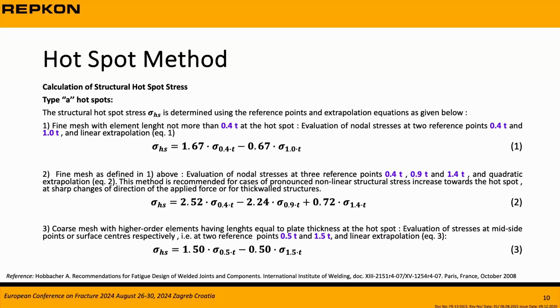Calculation of structural hotspot stress, type E. Fine mesh with element length not more than 0.4 T at the hotspot, and evaluation of nodal stress at two reference points, 0.4 T and 1 T, and linear extrapolation. This is the first equation.